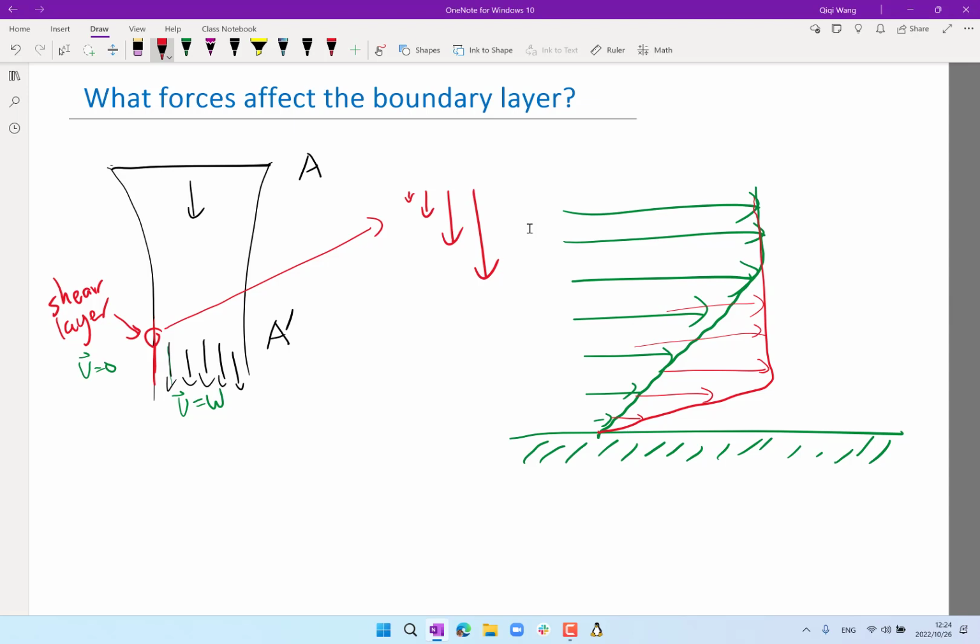When you zoom into the boundary layer, the curvature of the airfoil looks flat, and whatever wall normal pressure gradient you have on this scale looks like nothing. Now, what's more important is the pressure gradient along the airfoil. So let's consider whether the pressure gradient along the airfoil helps or balances the viscous force.